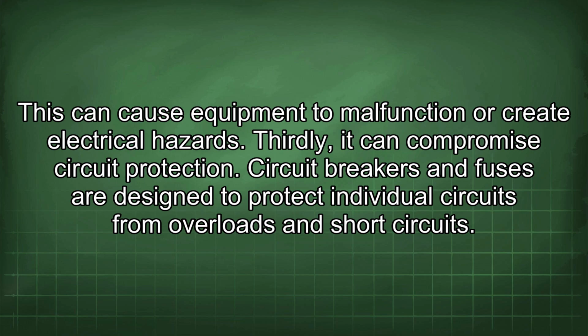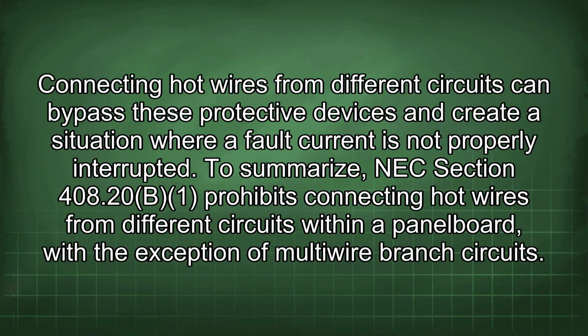Thirdly, it can compromise circuit protection. Circuit breakers and fuses are designed to protect individual circuits from overloads and short circuits. Connecting hot wires from different circuits can bypass these protective devices and create a situation where a fault current is not properly interrupted. To summarize, NEC Section 408.20 prohibits connecting hot wires from different circuits within a panelboard, with the exception of multi-wire branch circuits.